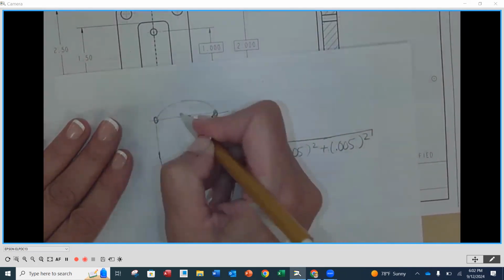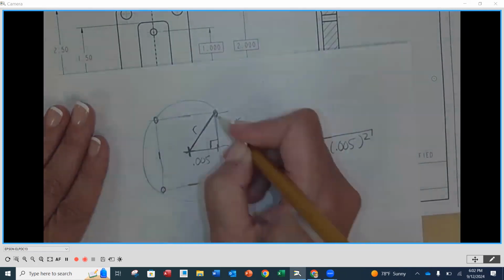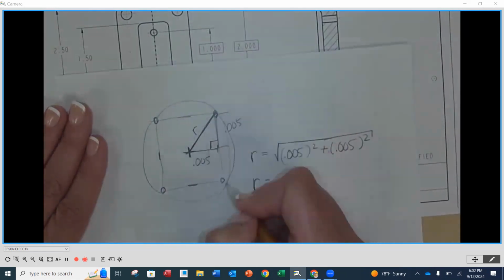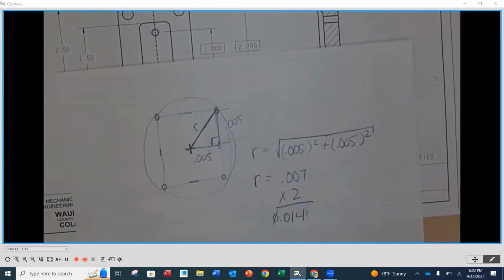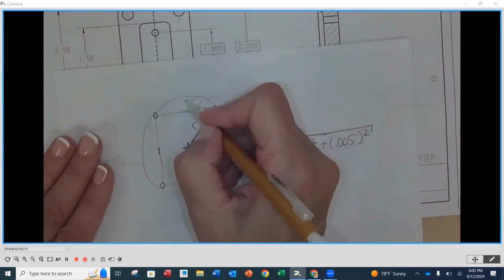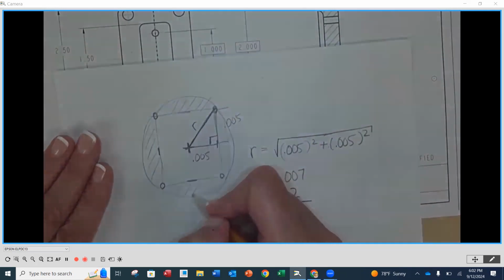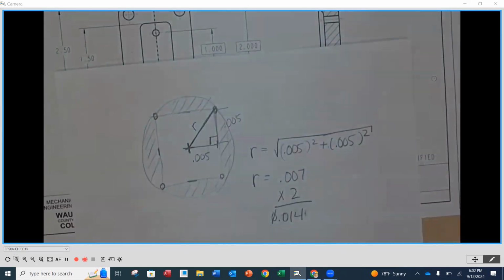So what we create is this arc going all the way around, right? And what it allows for us to do is by just taking that rectangular tolerance zone, knowing that those 4 corners work, then that means that all of this area is also going to work, right?